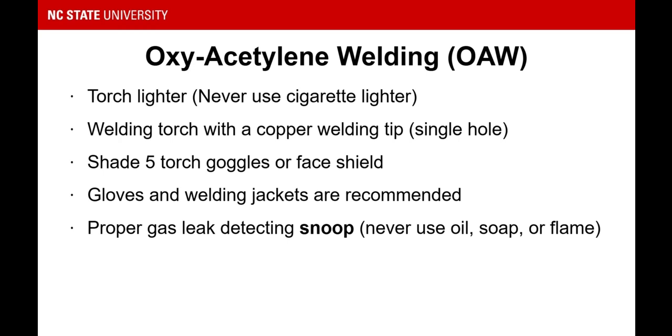Snoop is a product that does not contain oil, soap, or any type of component that is flammable, for testing oxyfuel setups. So basically you pour it onto the hoses or into where the fittings join up, and you look for it to bubble. If it bubbles, that means you have a leak. You should never use a lighter to try to find a gas leak, either. I know I've done that sometimes on propane setups. Not a good idea. You should use Snoop.